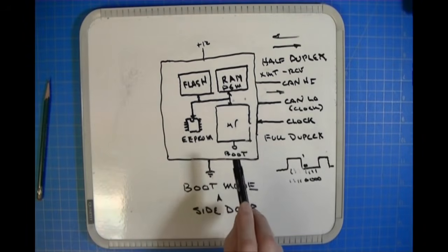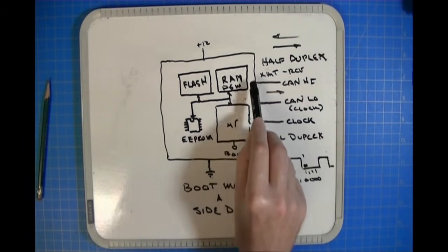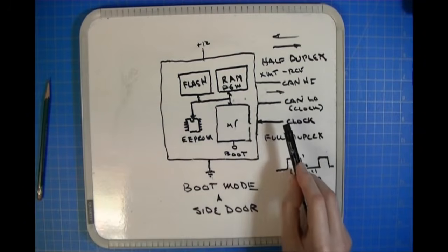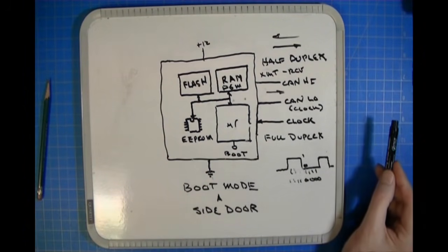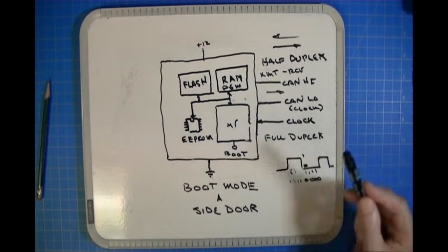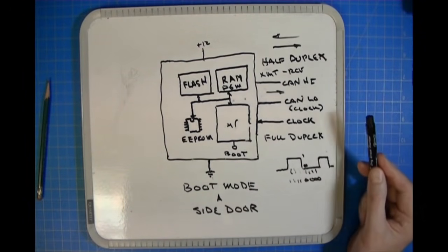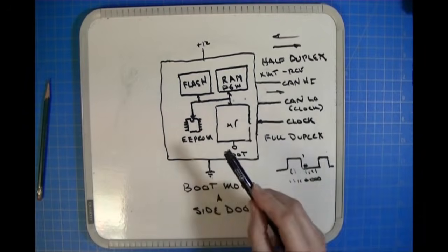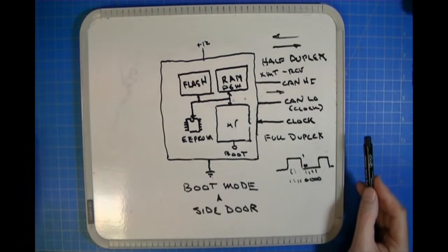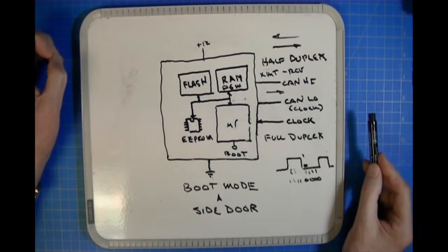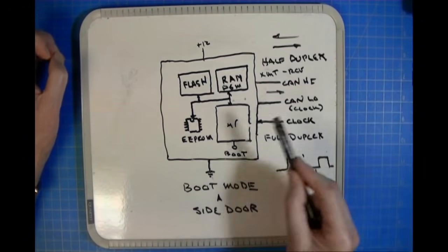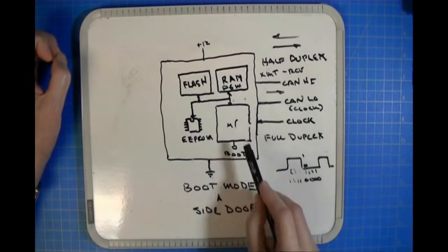The software interface is the program which is running in RAM, which was uploaded from the tool into RAM, and then the way that it works is when the tool first starts, and you select the boot mode on the tool, the tool will then, based on the processor that you've chosen and any other parameters which you have defined, select the right communication program, and it will send it up to the processor, which then sticks it into RAM.